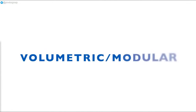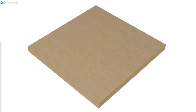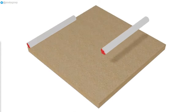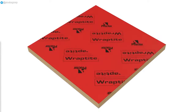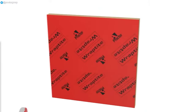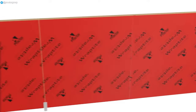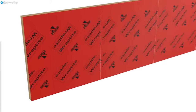The last option we'll consider today is using volumetric construction methods, where building panels are assembled into completed modules in the factory. They are then transported to site and assembled into the final building configuration. In this type of construction, the modules can be pre-fitted with all the services required, and depending on the final cladding choices, can even be pre-clad, requiring only the junctions between modules to be completed on site.